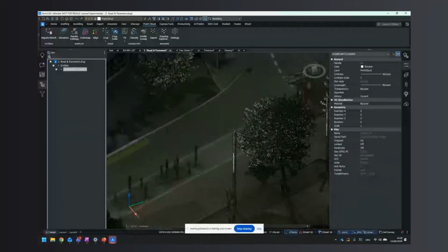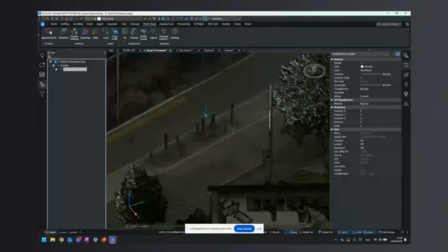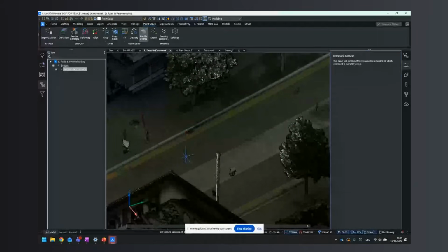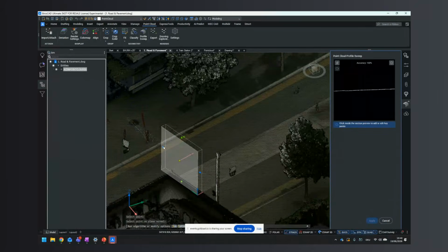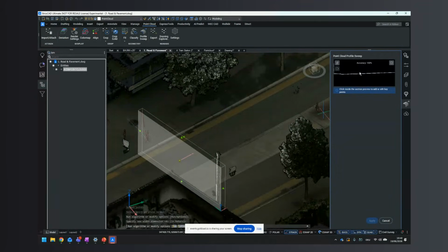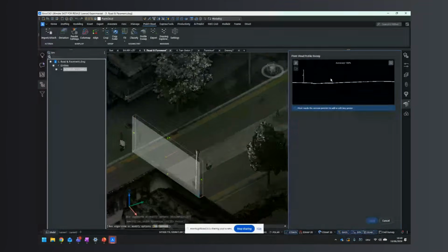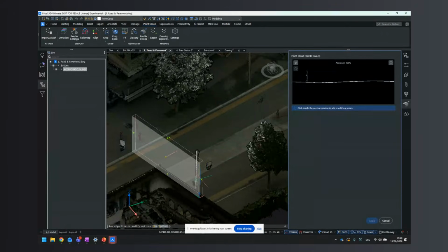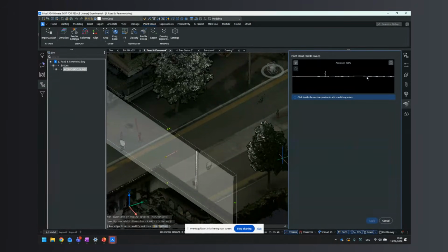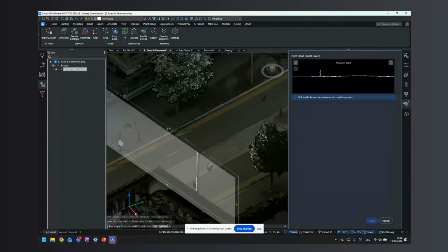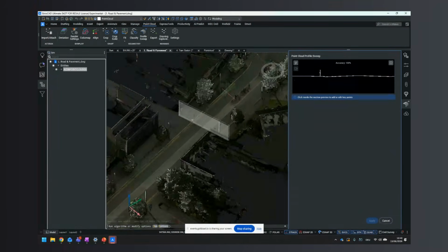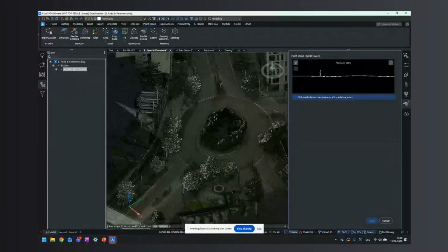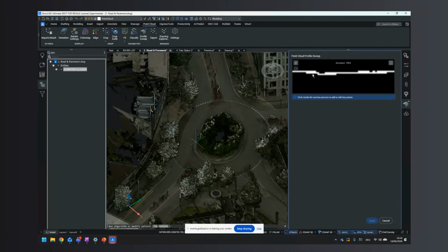Now here's the problem. Once we insert the profile sweep, let's do it somewhere here in the middle, right? The bigger the section, the smaller the resolution right here. So I highly recommend doing it in segments, because once you create a big section, you cannot be very sure where the line is.